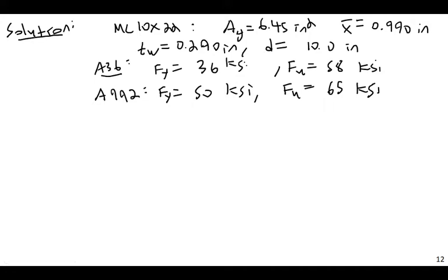We are going to have to go back and borrow some things from our earlier unit, our first unit on tension member capacity, because this is a tension member. So the first limit state I'm going to investigate is GSY, gross section yielding. Phi t, that would be a phi for tension times Pn.